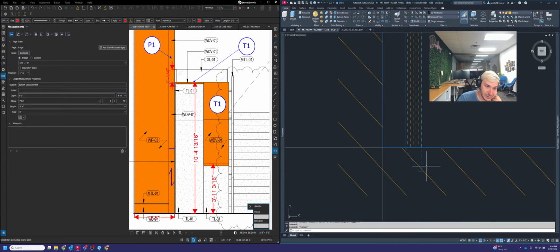Scribe, again, just to recap what that is, it's going to allow the installer to make sure that the panels are level with the floor. A lot of times it's used on base trim because if a floor in a building is uneven, unlevel, they'll use that scribe to make sure that the base trim or the top of that panel is all level across the top, even if the floor isn't level. So they will take the scribe and they'll trim it down to whatever that needs to be for the panel to be level, even with the floor being out of whack.